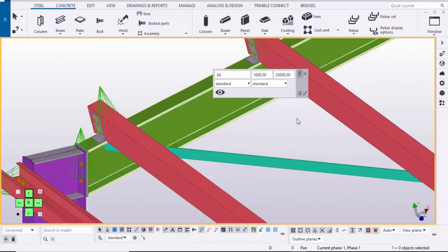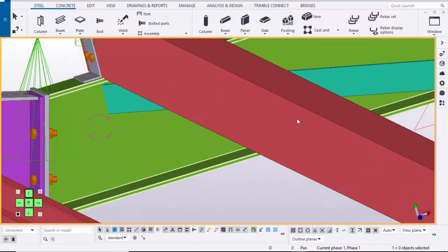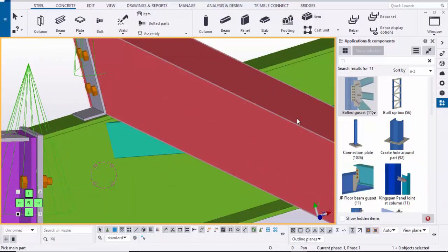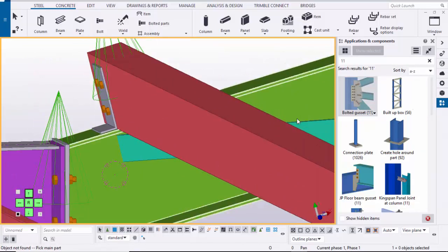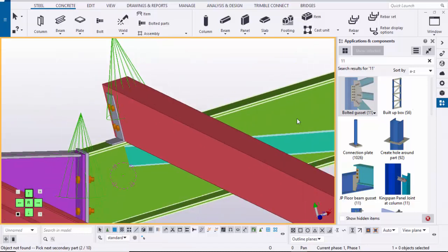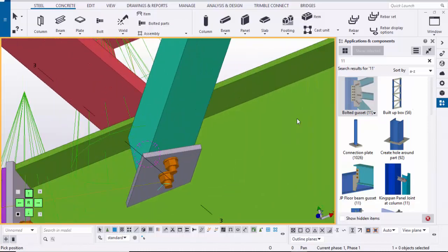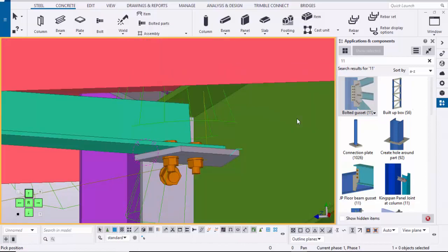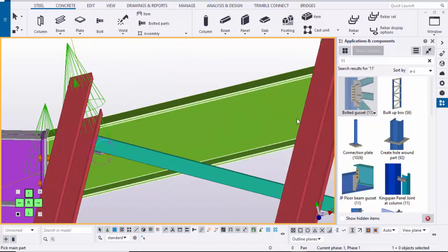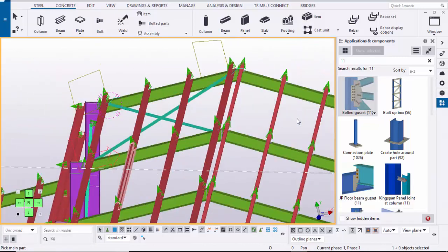Now we're going to create the connection between rafter to angle brace head here. So go to application components and select this bolt, and pick the rafter first, and then select this angle, then press scroll middle button to create this connection like this with the default value. Previously we selected, applied the values like this. Okay, we need to apply the same method at every junction, at this side also.